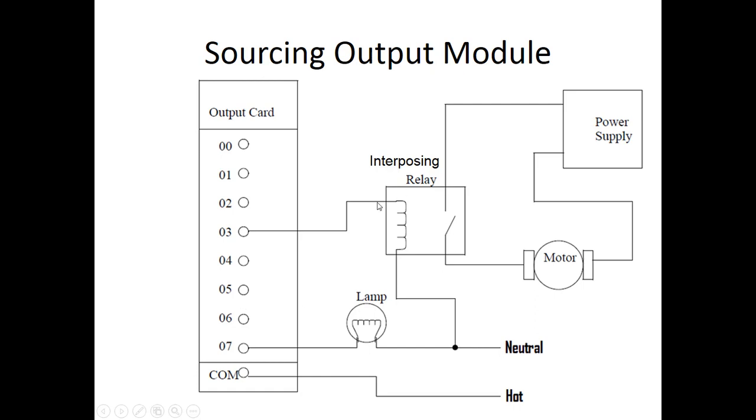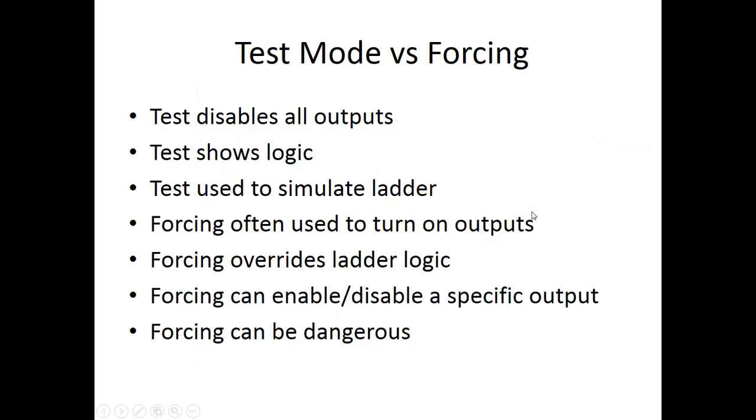This one here shows the interposing relay that we talked about. This relay can turn on, it doesn't take many amps to fire this coil, maybe half an amp, which is what this is rated for, or less. And that closes a switch, and this circuit over here can be very heavy duty with a high ampacity, and it won't affect or burn out the card.